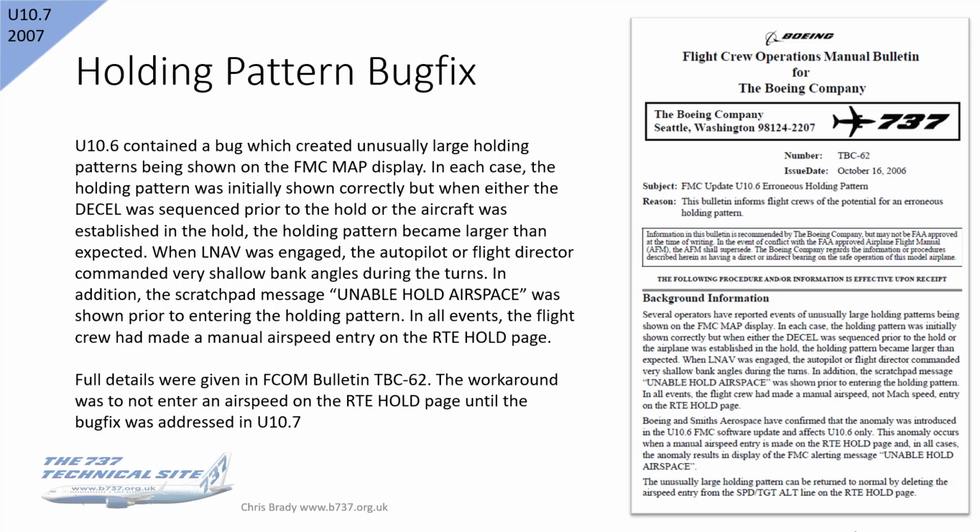And when LNAV was engaged, the autopilot flight director commanded very shallow bank angles in the turns, which would take you outside of the holding protected area, and hence you got the scratch pad message, UNABLE HOLD AIRSPACE. So again, the bulletin was issued.